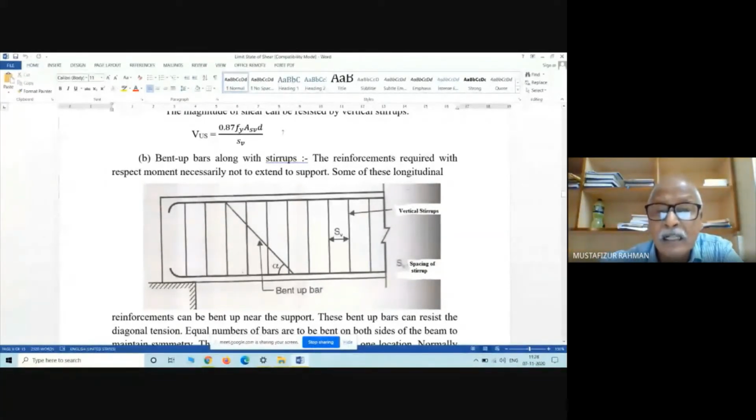So see, these are the rods. This is a section, and this is coming from this way. Now, this reinforcement at the bottom: I already told you that since bending moment near the support is zero, and bending moment from midspan to the support gradually reduces, whatever reinforcement is provided for the maximum bending moment at midspan need not be required throughout the length.